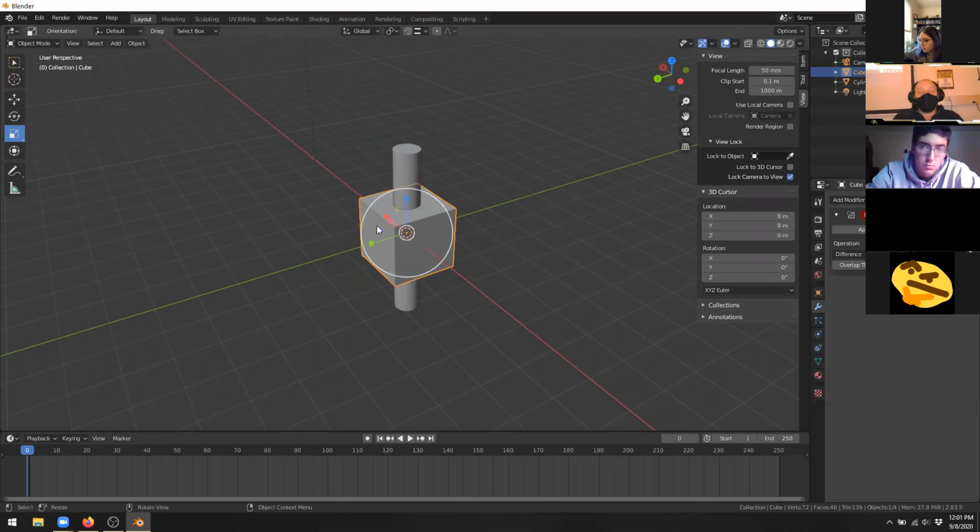And again, it doesn't matter what you have. It could be a cube that's halfway chunked into the other cube or part of a sphere. The one thing I'd say is, whatever you choose, it shouldn't envelop the entire model. It should only overlap with it in a smaller area of the whole. After I take care of that, I'm going to go back and single click on this cube again so I can access the modifier properties for it.